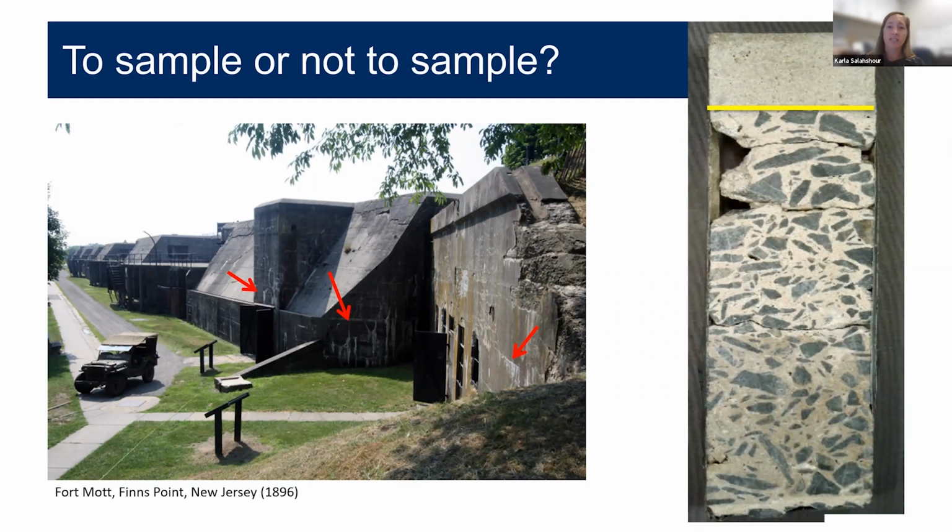The walls were constructed of mass concrete, and at the time of construction, there was no way to mix and place these large batches of concrete. And so we had a lot of cold joints in the walls. And in the field, we saw that the efflorescent staining was a result of moisture migrating through these mass concrete walls at all of the cold joints.